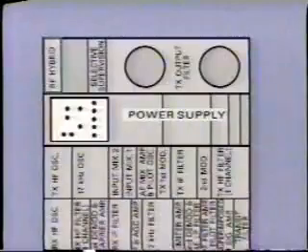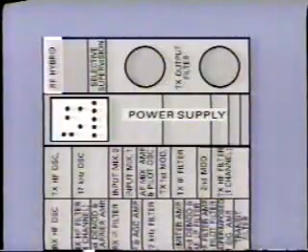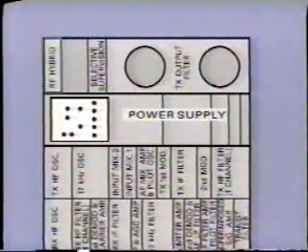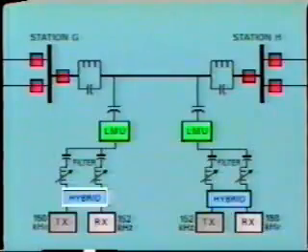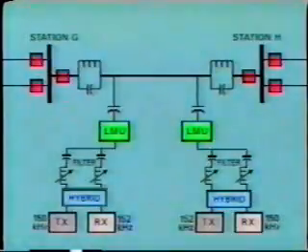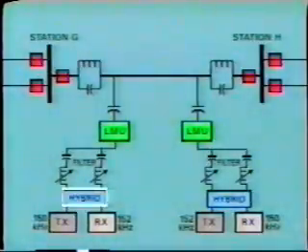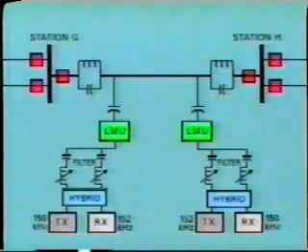At the top left of the cabinet is the RF hybrid module. As you know, this is where the transmitter and receiver frequencies are segregated. The output from the hybrid is connected to the coaxial cable running out to the LMU in the switchyard. The hybrid needs adjusting during carrier installation to allow for actual line impedance.